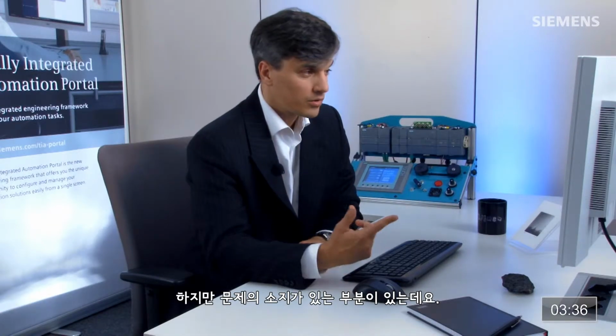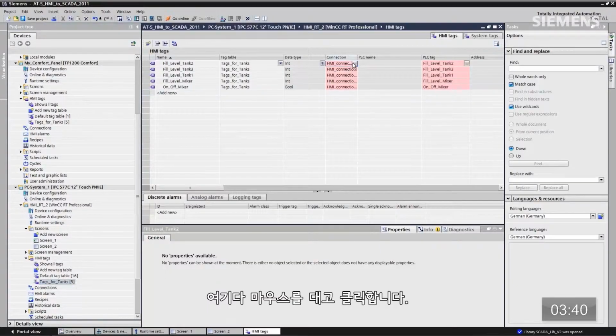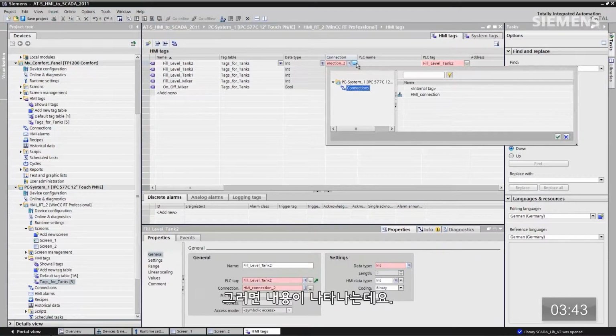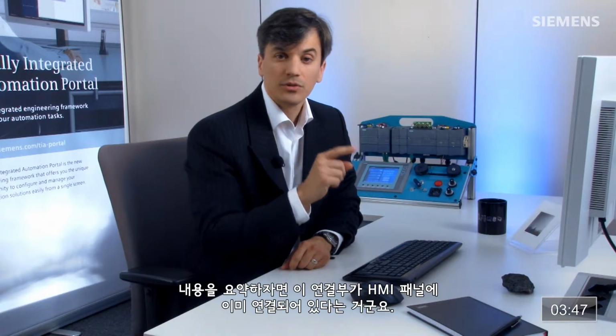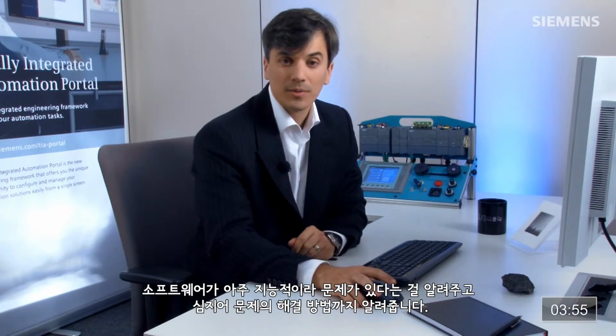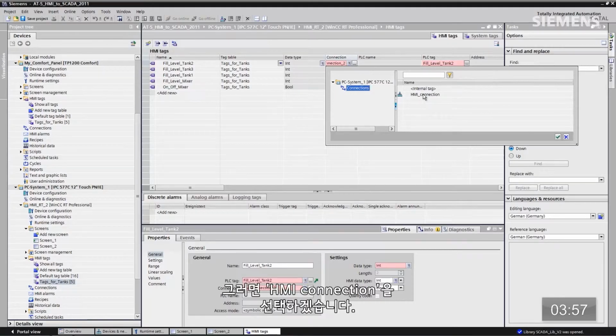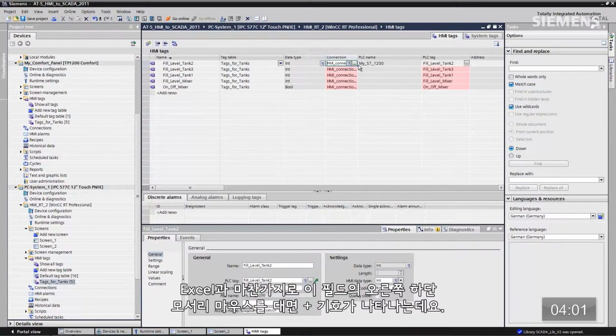Here's our tags. However, we have something potentially wrong. They've highlighted the connections in red. So let's go mouse over that and just click on it and go show that. So basically what it's saying is we've already got this connection going to the HMI panel. We have to create a new HMI connection to the SCADA system. The software is so smart, it's actually telling us there's a problem and even gives us an option to fix the problem. So let's actually choose the HMI connection, click the OK button,